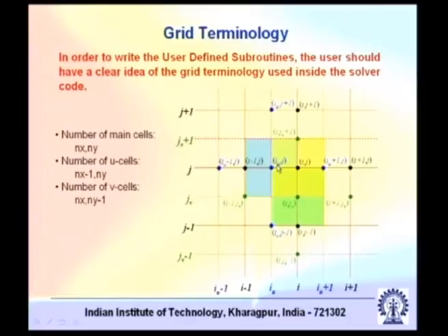In this particular figure, wherever you have I with subscript u, that indicates the index where you are solving the x momentum, u momentum equation. Similarly j with index v will indicate that you are trying to solve for the y momentum equation. So I index for x momentum and j index for y momentum, and in this particular example we are using certain nomenclature. It may be better to introduce that.